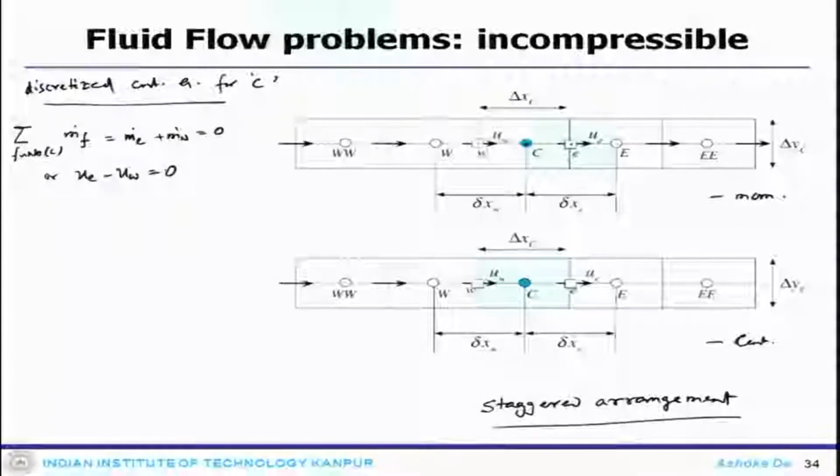So, you do not need to do any interpolation, as I have stored the components at the cell faces, you do not require to interpolate anything here.